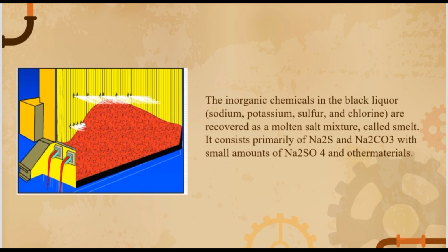The inorganic chemicals are much heavier than the combustion gases and tend to fall toward the hearth. One feature of the recovery boiler is the presence of the char bed on the hearth. The char bed consists of a pile of partially pyrolyzed black liquor solids, carbonaceous material, and inorganics that accumulate on the hearth. Not all of the inorganic chemical proceeds directly to the hearth.